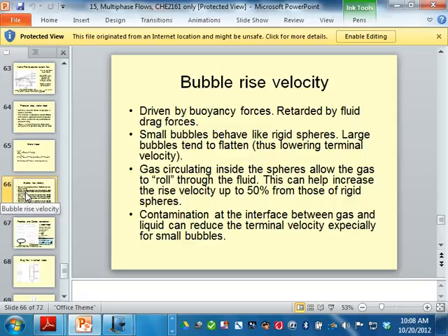At the bubble interface, there's surface tension, and even the slightest amount of contamination will change the value of the surface tension. So sometimes what you predict and what actually happens is quite different. Surface tension is very sensitive. Even the slightest amount of oil or other contaminants, surfactants, whatever, inside your system, it won't behave like distilled water and air anymore.